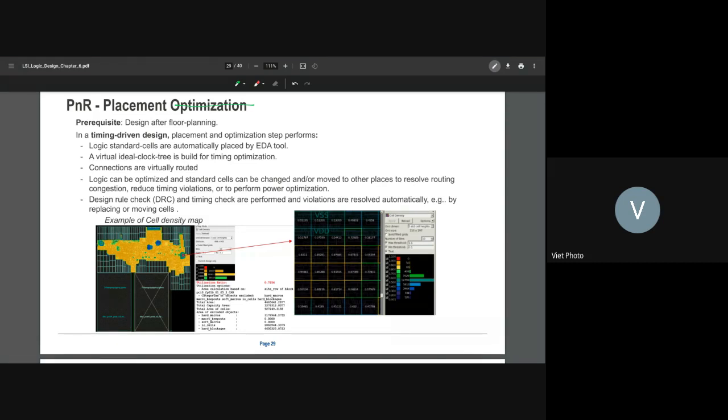The cell delay is all one thing, in that the wire delay affects the cell delay. Remember, when the wire is long, the cell delay will be higher too. And when the wire length is long or the wire width is narrow, there are basic things to consider with the wire delay. First, the length. Second, the width, right? If the length is longer and the width is narrower, then we have more resistance and more capacitance.